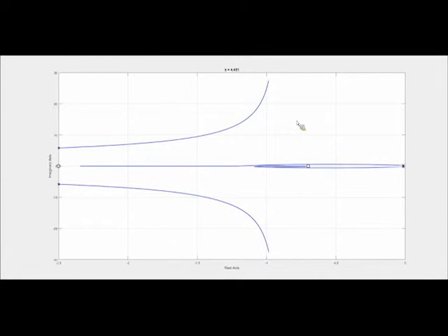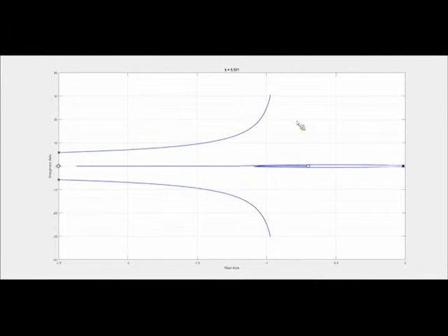And then in recitation, I understand that you went through some observations. The main observations are going to hold for everything. It's not like we're just making observations that only hold for this case. They'll hold for every root locus system we see. The plot is always going to be symmetric about the real axis.